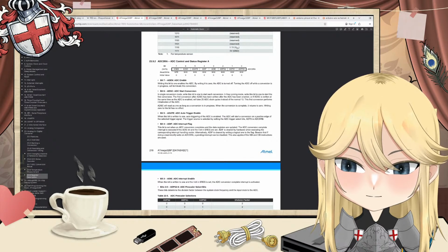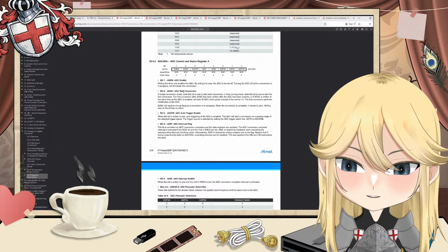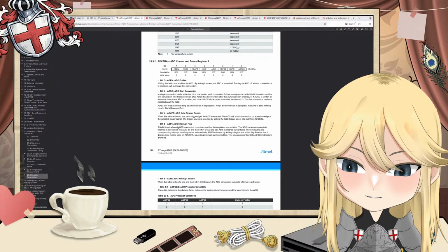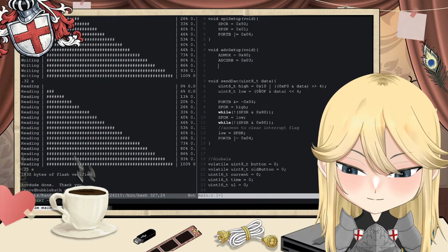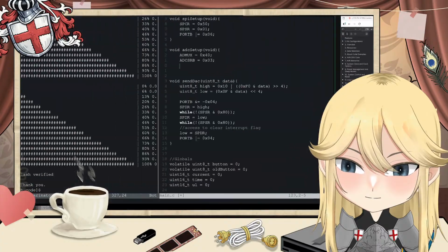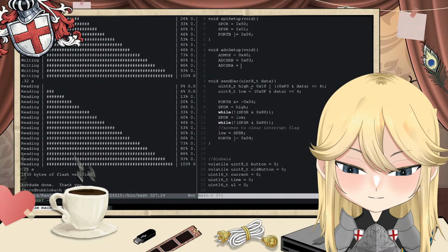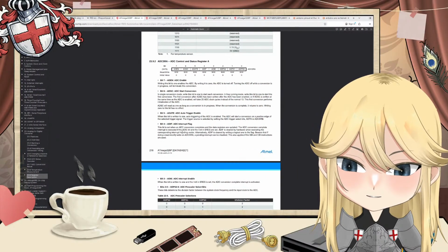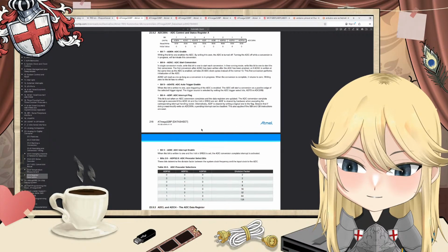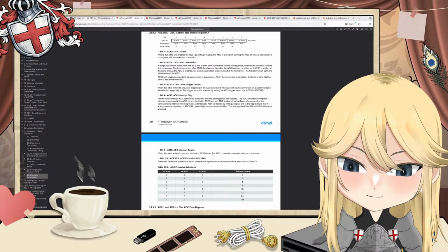Which did we, well, what did we say? Auto trigger enable, yes. 1, 1, 1. Interrupt flag 0. So E. Oh, copy this. Equals 0xE. And the other one was interrupt enable. Kinda want to do that, yes. Prescaler 0.